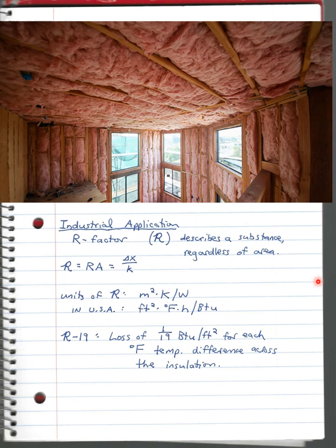This is a different R. So the R factor, I'll write it as a script R, describes a substance regardless of its area. The R factor is that R that I just told you about, the thermal resistance times the area. And it's equivalent to, here's the important part, the thickness of the material divided by its thermal conductivity.